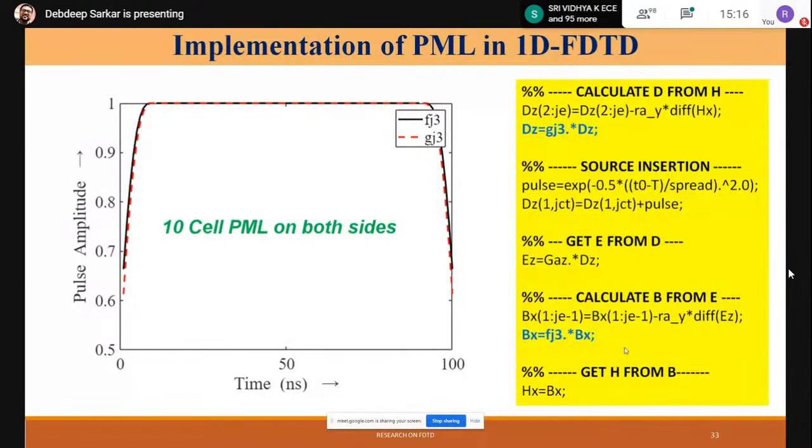But from a very physical point of view, from an antenna engineer's point of view, what is actually happening? Think about antenna measurement. We do it in an anechoic chamber. Why do we do that? To prevent echoes from the walls. To do that, we put absorbers. Many of the present researchers, many of my colleagues and my supervisor work in the domain of absorbers, so people will know a little about how to implement absorbers for a practical scenario. But now we want to borrow that knowledge into building perfectly matched layers in our boundary.